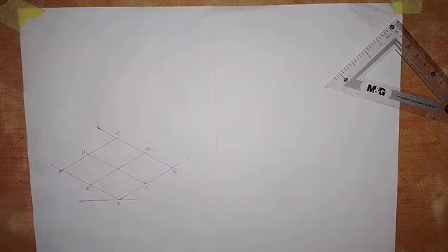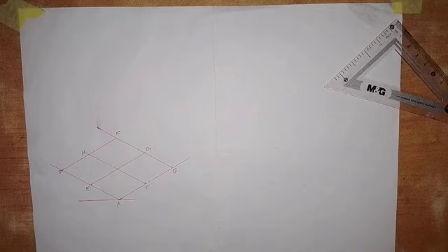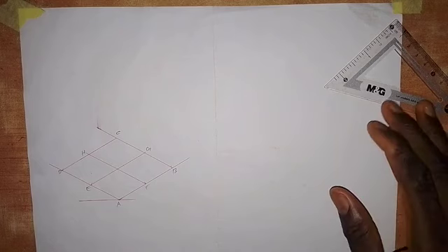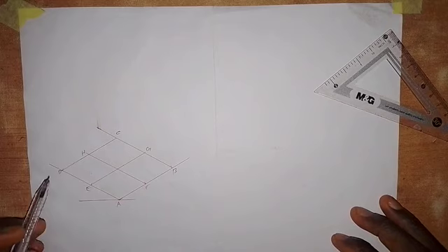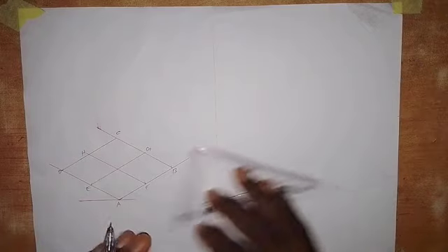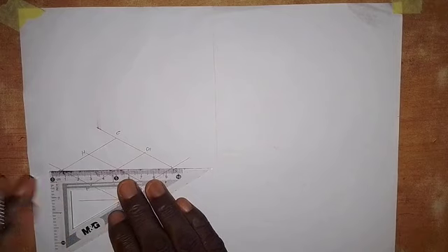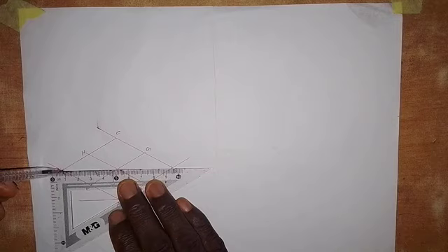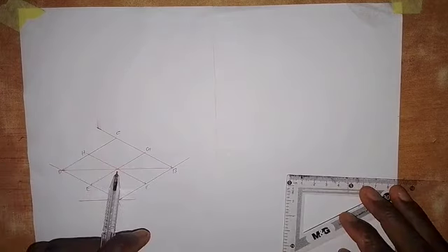Alright, so where are the 4 centers that we are to use? That is what I want to bring out now. So what you have to do first is that you join the longest corner together. So this corner and this corner, they are far from each other. So you have to join them together with a straight line like this. Join the longest corners together with a straight line. So it goes like this. And the line should pass through the center, where that is the center here.